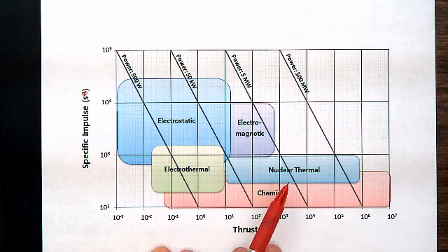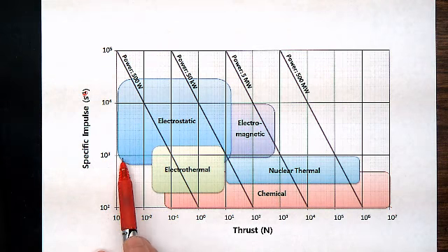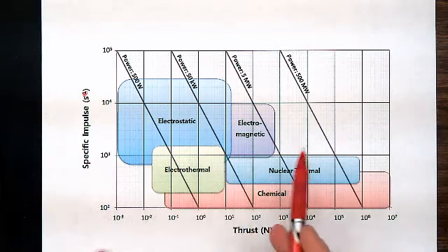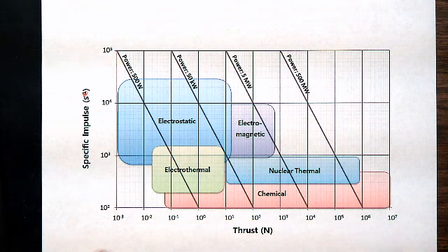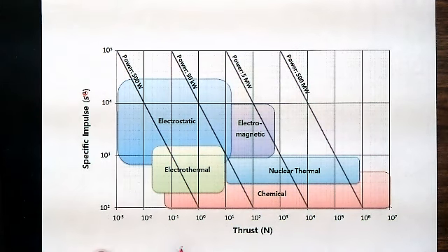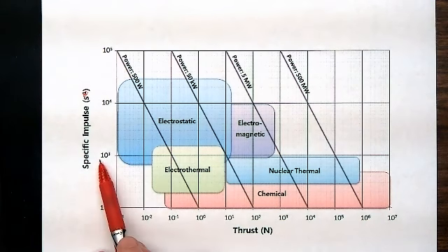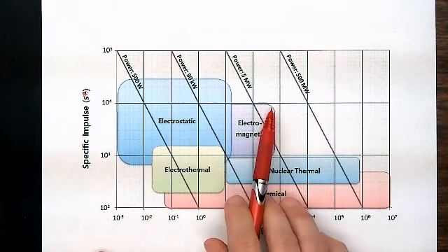But you can see here that thrust levels on electrostatic systems, and these would be used on regular, normal sized satellites, are on the order of 1 millinewton of thrust, compared to a chemical system that could be a newton or a quarter newton. That would be very small. But notice that on the specific impulse scale, on electrothermal systems, you can get close to 1100 seconds.